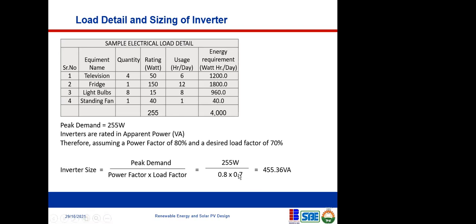Can you just spend 1 minute? Okay, go ahead. The engineer, I don't know the name of the engineer. The 70% is also like what we discussed yesterday. It's another safety factor. In other words, you don't load your generator 100%. Your inverter will not be operating at 100%. So this 70% is like you are saying, at every point in time, I can load it to 70% maximum.